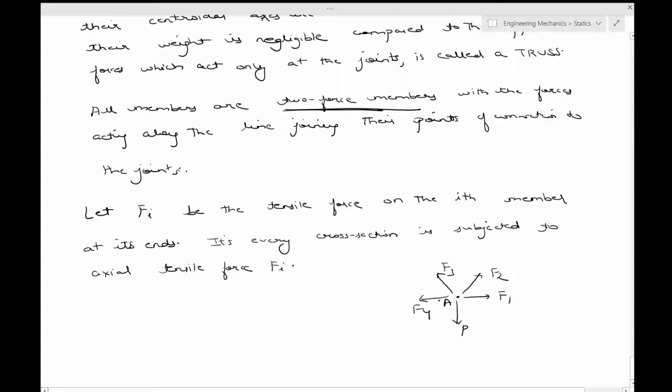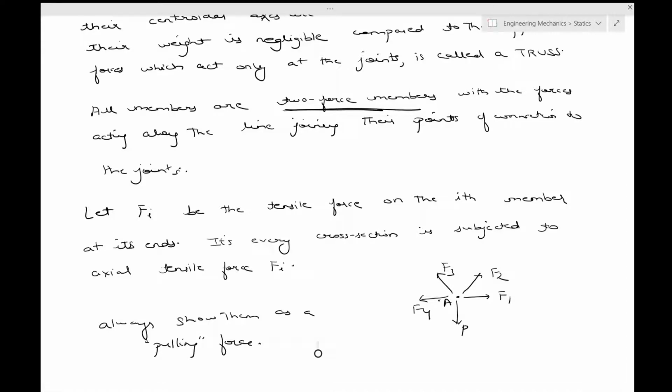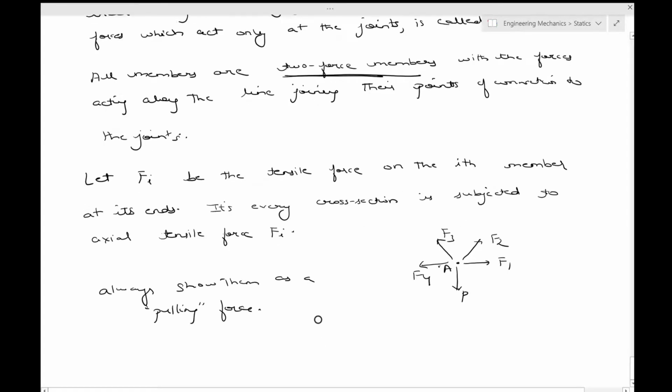Okay, so always show them as a pulling force. Obviously, if after you apply the equilibrium equations the answer comes out to be negative, in that case you can just reverse it, and then you know that the actual force is not pulling but it is compressing.